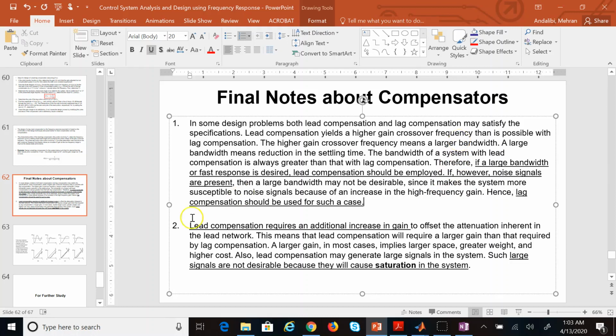So that is important. One other drawback of the lead compensator is that it typically needs high gains. It will lead to large gains overall in the system. And large gains, when you want to physically create them, not just in simulations, a big physical gain means basically larger controllers, more space, more cost, more weight. And also many of the systems can only provide so much current, voltage, and input, and after that they would saturate. So it can lead to saturations as well.